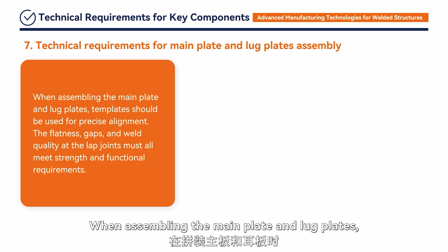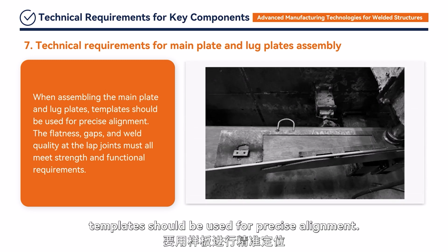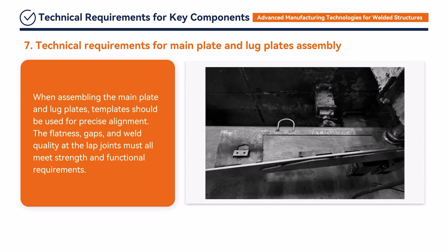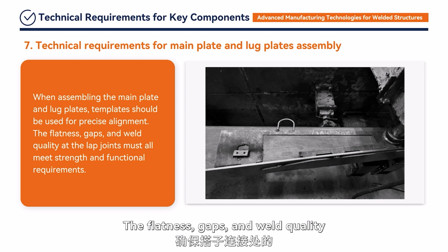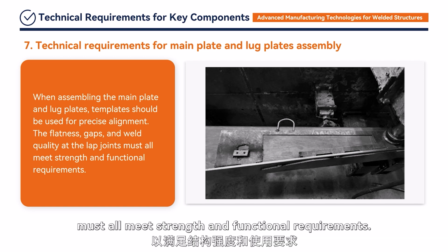When assembling the main plate and lug plates, templates should be used for precise alignment. The flatness, gaps, and weld quality at the lap joints must all meet strength and functional requirements.